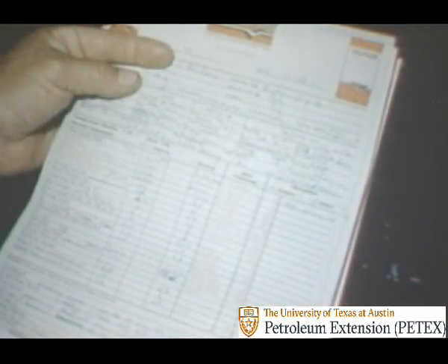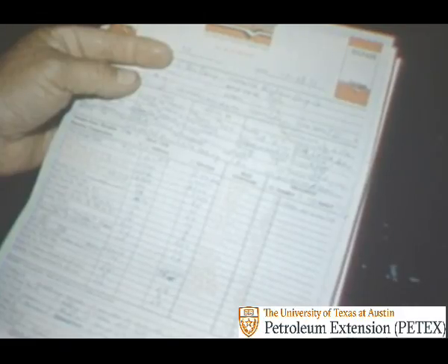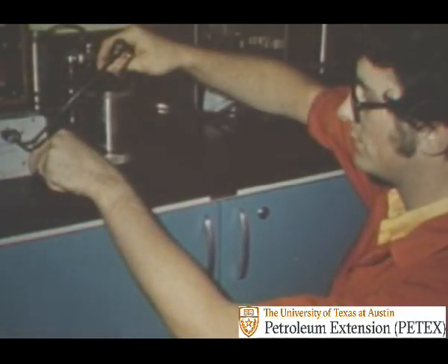Mud companies usually use a special oil mud report form similar to this one because some of the tests are unique to oil muds. For example, an electrical stability meter is used to determine the emulsification of the water in the oil mud. Oil does not conduct electrical current, but by immersing the electrodes in the mud and increasing the voltage, current can be made to flow. The more voltage it takes to establish electrical flow, the more stable the emulsion.